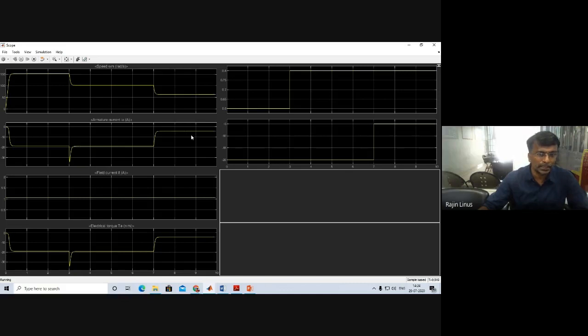So now what happened? Even though the load torque is minus 5, we have to apply the duty cycle of 0.8. So the on time is more, and the armature current will increase. That is why it is... sorry, I'm extremely sorry. So here, the armature current is initially minus, approximately 20. Then again it reaches 20. The reason is we have not changed any load torque.